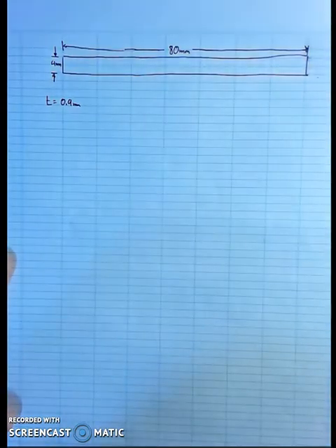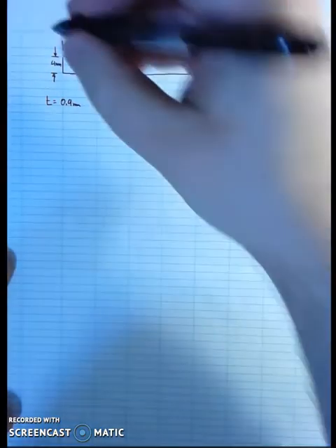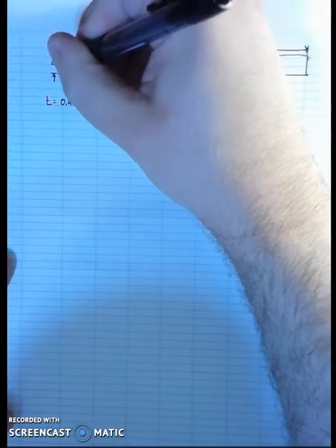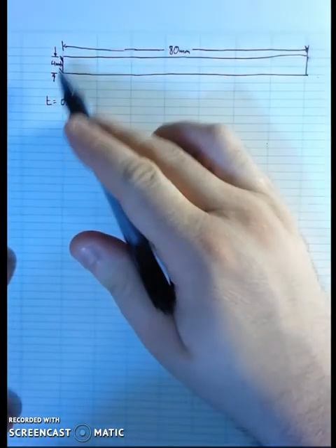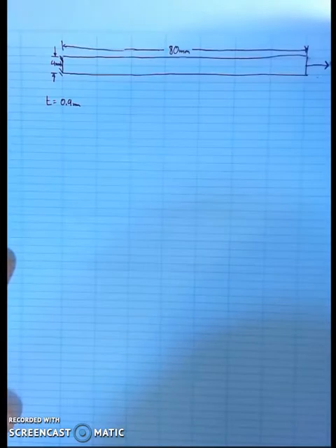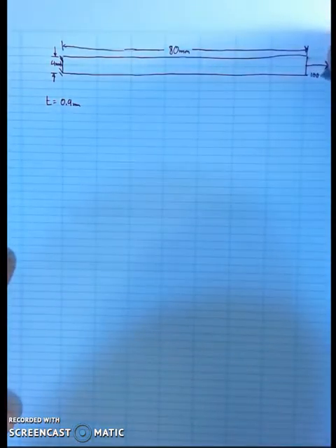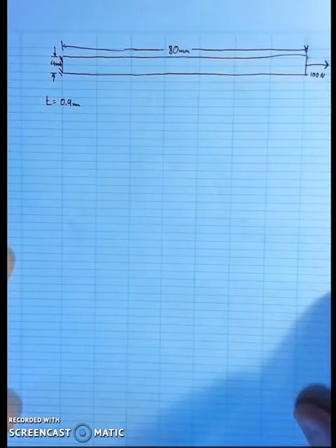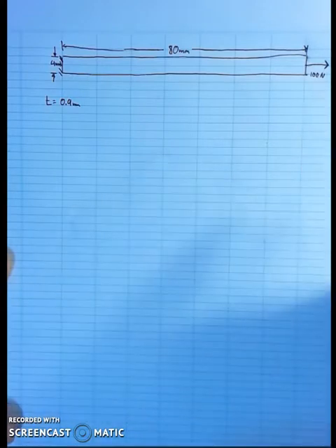Now, what I do when I run these things in a real experiment is I clamp them down and then I impose an external force. So I'm going to draw a symbol here that indicates that I've clamped this end so that it can't move. And on this side, I'm going to impose a force of 100 newtons. If you've actually run the experiment, you know that the PASCO stress strain apparatus can impose a force on the sample of up to 250 newtons. So 100 newtons is a pretty modest amount, something that's definitely achievable by the PASCO stress strain apparatus.